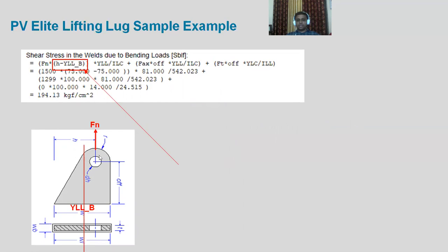So you can see over here that this eccentric distance can create the bending moment. If it is exactly at the center, then there will be no bending moment coming because of this. But if it is not exactly at the center, there will be chances of bending moment because of normal force also, correct?